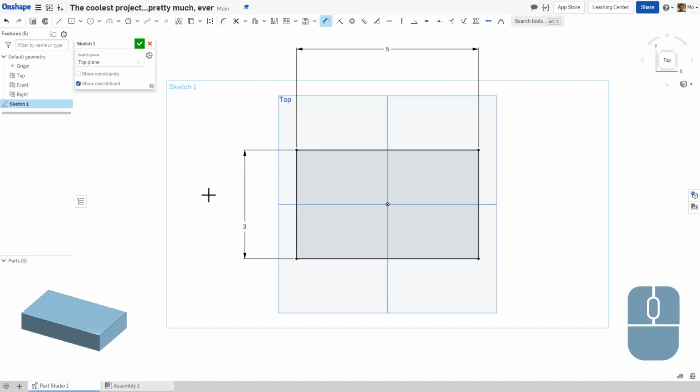So this is kind of a trivial example of this, but it shows that we can not only put arbitrary units inside of dimensioning tools, inside of these bubbles, but we can also put basic arithmetic. Pretty neat. It's like a little notepad. If I'm ever curious as to how I got to 3 inches, well, I can come in here. Oh yeah, I multiplied 2.54 centimeters times 3. Great. Okay. So we now have our 3-inch by 5-inch rectangle centered on the origin.